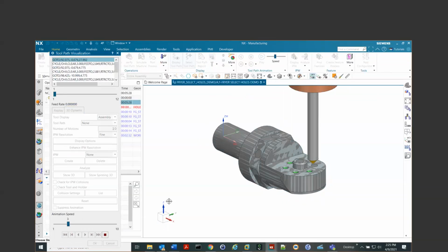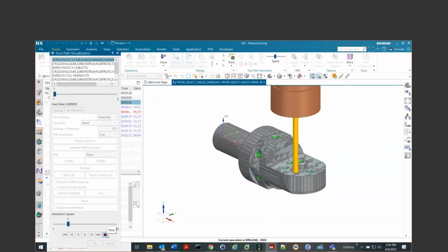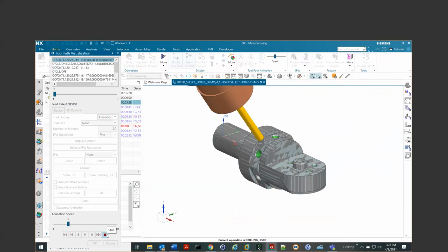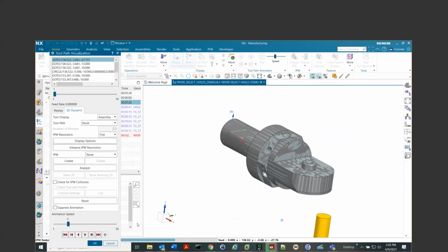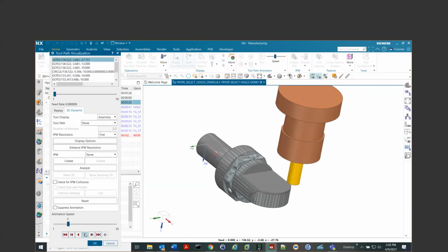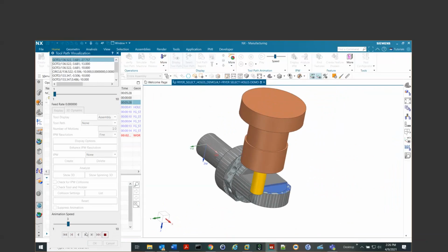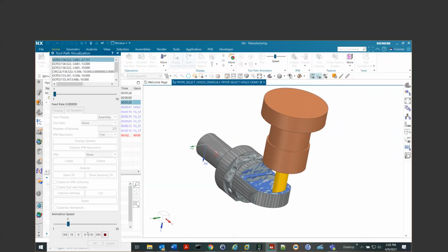And this is going to be doing a volumetric material removal. Putting the right size drill in the right hole here. Letting the holes dictate the index. I'm going to stop it here, flip it over real quick. Hit the play button. And now we machine the flat in the pocket, taking a finished cut on the walls.